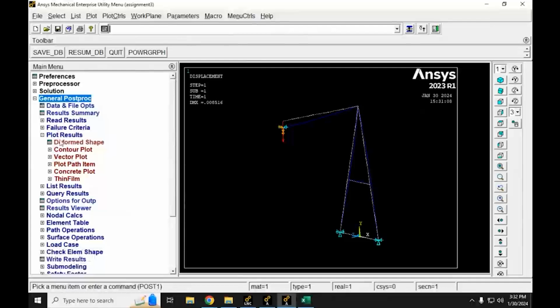And now let's take a look at the deformed shape. This is what the deformation looks like. Again, it's exaggerated. The deflection is only 4 millimeters, 4.4 millimeters, 4.5 millimeters. And again, the units on that are meters. So if you multiply times 1,000, move the decimal over 3 places, you're in millimeters. It's displacing 4.4 millimeters.